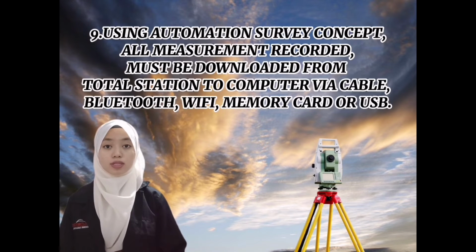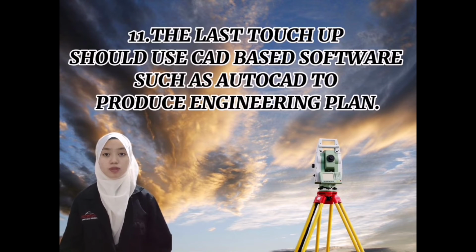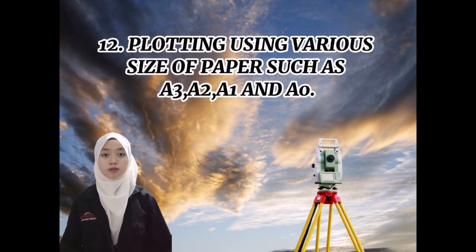9. Using the automation survey concept, all measurements recorded must be downloaded from the data station to a computer via cable, Bluetooth, Wi-Fi, memory card or USB. 10. The data can be processed using survey software such as Civil Design and Survey CDS. 11. The last touch-up should use CAD-based software such as AutoCAD to produce the engineering plan. 12. Plotting using various sizes of paper such as A3, A2, A1, and A0.